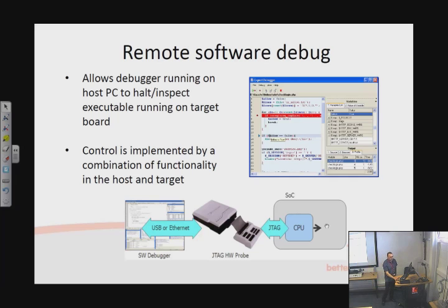And we can look into the mind of this target device, which is executing over there with no screen or keyboard or anything like that. We can actually understand what's going on. So here we've got an example of somebody set a breakpoint and we've checked and it's stopped executing when it's hit this particular line of code to find out what the variables are. For example, we could understand exactly why the device had entered that particular set of code, set of instructions.